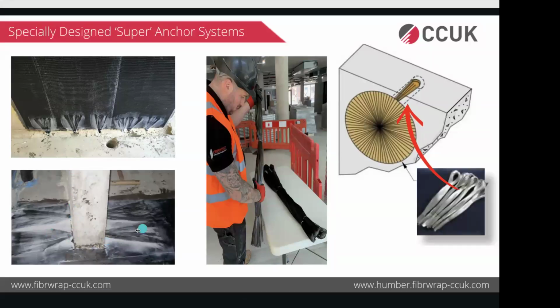So in this instance, we drilled a hole through the column, used these bigger anchors, passed them through that drilled hole, split them on both sides like a dovetail, and put one more layer on top of it. So now after curing, these anchors become a tie, which is transferring force from one side to the other. Or in other words, you've got a continuous top reinforcement in that location. So that's how you should do the hogging moment strengthening using carbon fiber with a proper anchorage detail.